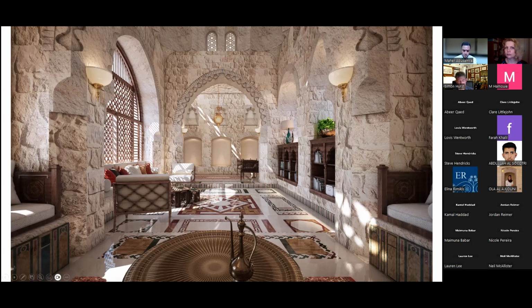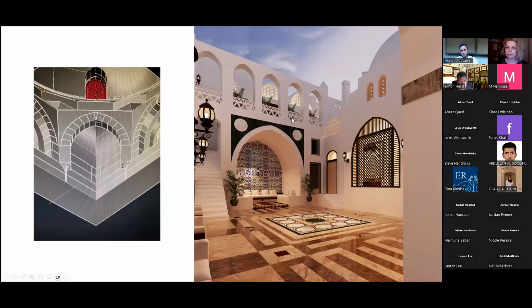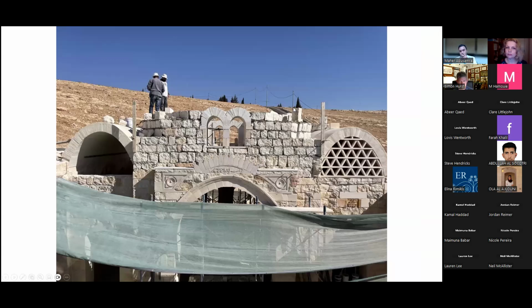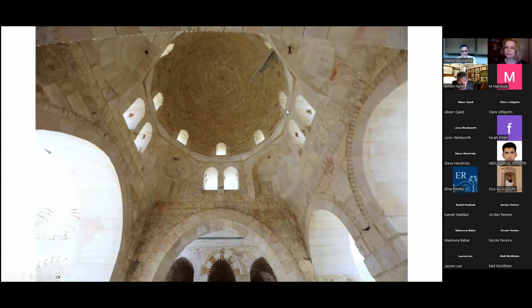And I think in INTBAU, especially Robert is doing some work, and they had a big gathering in Venice just to change the ICOMOS report and say that traditional sites have to be reconstructed or added to with the same construction technique, because there were problems in Spain where after the earthquake, churches were restored in concrete and steel. And then when another earthquake came, cracks happened between the old building construction and the new building construction. So I think this is something that has to be reviewed by UNESCO and ICOMOS, and how to say that, no, we cannot use new building material in old sites.